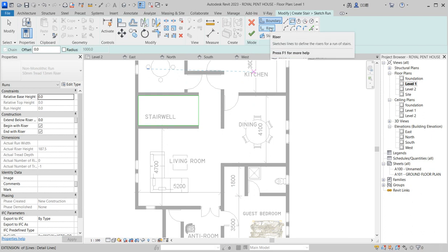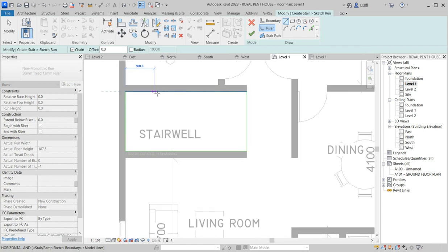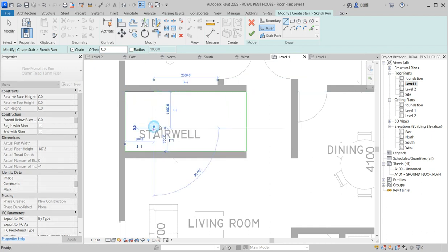After that, the next thing to do is to start putting risers in place. So you need to calculate very well. I always start from the landing because I need to separate the landing first before I go to my remaining risers. So the landing should be 1000. Yes, I just use that, or let me just use 900. Yes, so I'm using that as my reference.